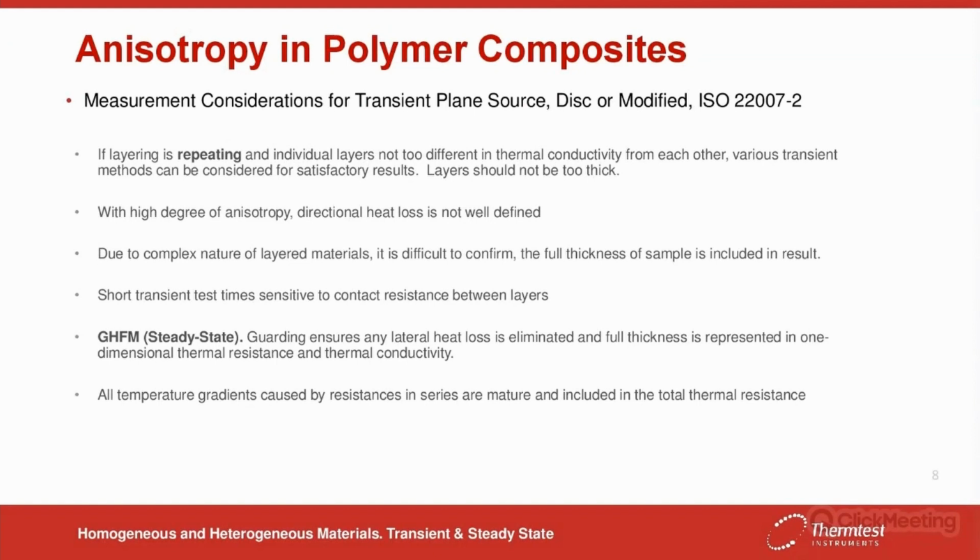Often the penetration depths calculated from raw data are based off the thermal diffusivity measured by that same instrument. So if there's error in the diffusivity results caused by not meeting the ideal theory assumptions, your penetration depth would be wrong. Therefore, it's really difficult to ultimately know that you're sampling the whole sample.